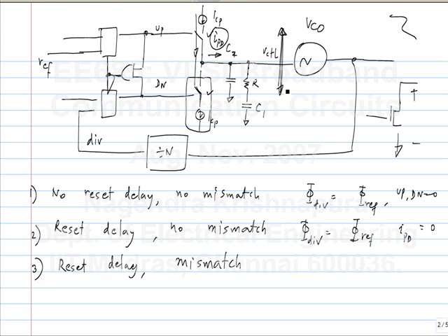Okay? So, if the VCO needs to be operated over a certain range, you have to have the current source also operate like a current source over that range. Otherwise, the mismatch will become too much. Let's say at the bottom of this range, this has gone into triode region. It's supposed to give you a current ICP, but it gives you something less. This is now a systematic mismatch, whereas this is giving you ICP because it is comfortably in the saturation region. So, there will be a big mismatch and big reference feed through.